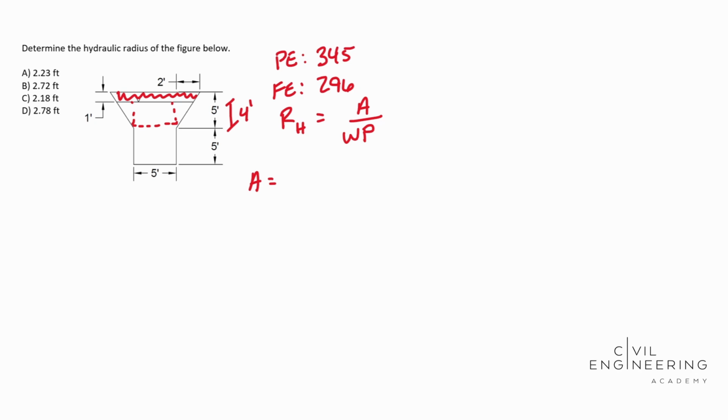So zooming in real quick to these triangles, you can really mess this up in multiple ways. We see that our water level is 1 foot below, like I said earlier. And so the depth, or the dimension here, is actually including that airspace. And so we don't want to do that, right? We don't want to include that. This guy's 4 feet. And so the way that we get by with this is we create similar triangles.